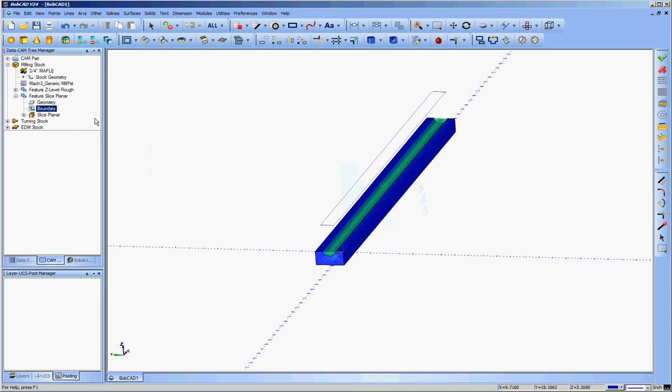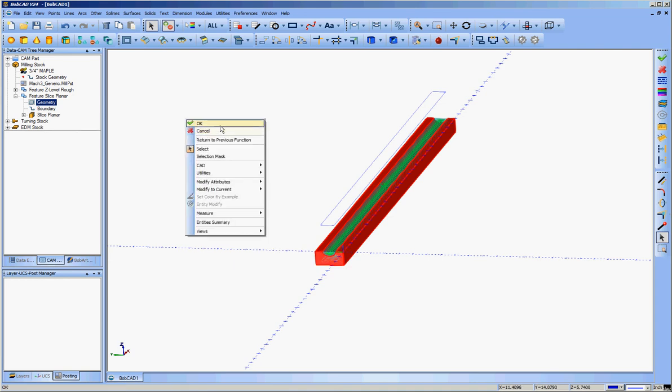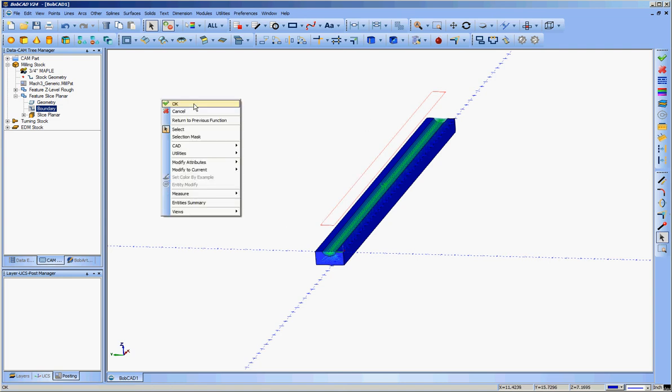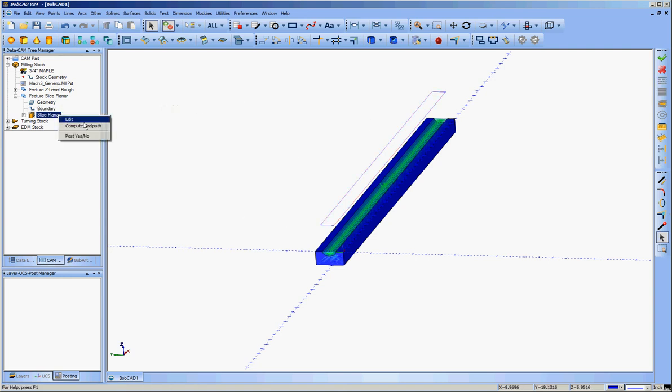That finishes that up. Again, I'm going through the tool pathing pretty quickly here because there's a lot to cover there. That's a matter for another time. Okay, reselecting my geometry, mold, that looks good. Reselect boundary, yes, my rectangle is still selected, that's good. Both okay. Compute toolpath. This is very fast because it's a pretty small number of lines. If the lace angle had been 90, that would probably take 2 minutes to calculate on my machine.